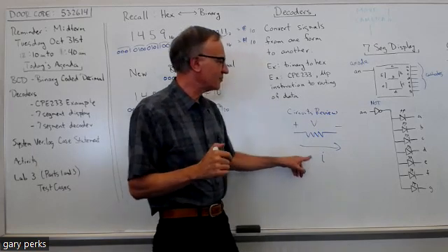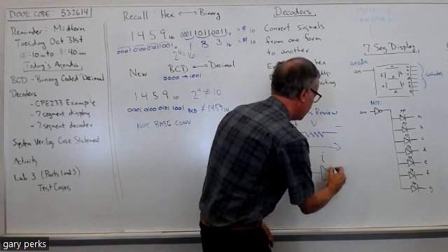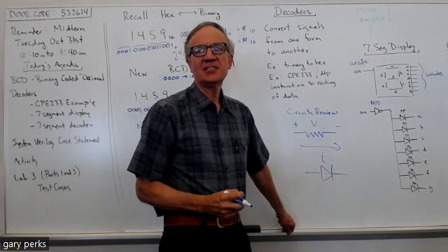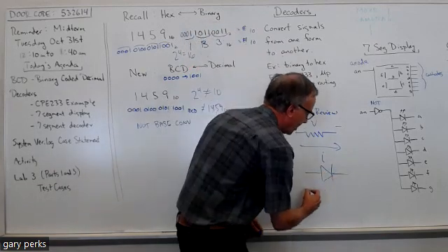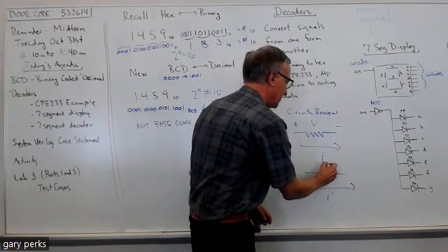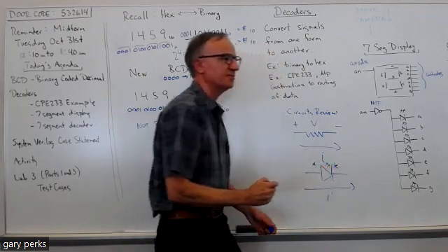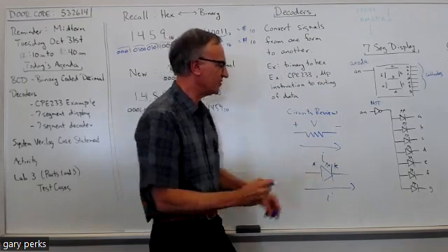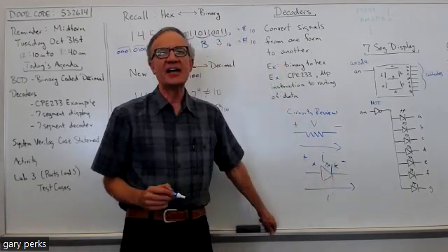Okay, the reason I bring this up is because a diode or an LED also can only absorb power. Diodes can't supply power. And positive charge flow through a diode or LED is always anode to cathode. To get positive charge to flow anode to cathode, you have to have a higher voltage on the anode side than on the cathode side.